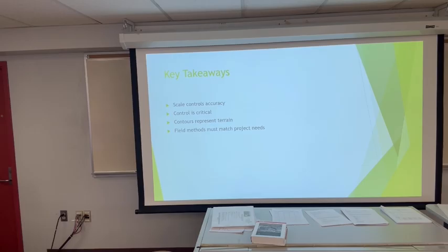And they're storing pallets and pallets and pallets of all their product, and they're running forklifts back and forth nonstop. So that's a problem when the floor is failing. We actually went in there on a Sunday, laid out a grid, and got elevations so they could determine, okay, what's where, how good is the floor, we need to get this fixed quickly.